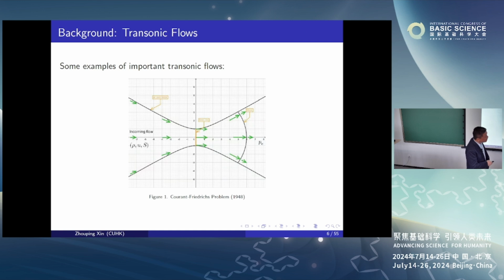But in engineering design, people want to design the geometry of the nozzle, given the Mach number of the incoming flow, so that they reach a very high exit pressure. The end pressure is prescribed to be very big. That's what we want to achieve. But if you want to achieve that, the flow coming from here, you see, this is the divergent part. Flow is supersonic, becomes more supersonic. By Bernoulli, the density will become less, then the speed will become less, and then the pressure will become small. So the pressure cannot reach the given pressure states.